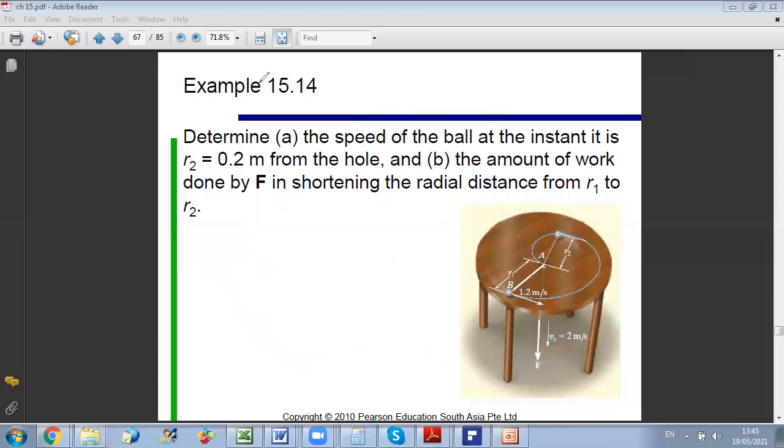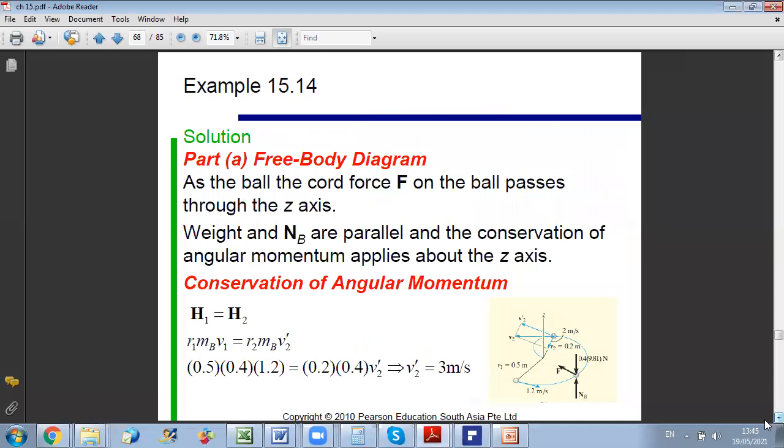And all of these can be seen here in the details of calculation. So the first step, as you can see here, we decompose the velocity into two components. One radial component directed towards the center, A, and one perpendicular to R, which is V theta. The component perpendicular to R is calculated from conservation of angular momentum. The component along UR is VC, okay?